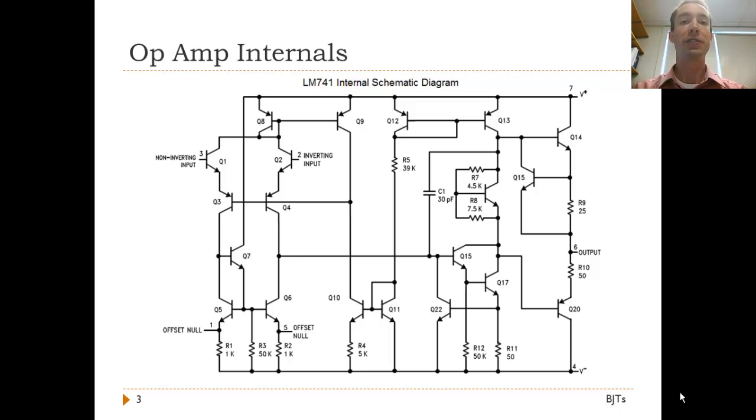An op-amp is composed of tens of transistors. The figure here shows the internal makeup of the very common LM741 op-amp. The different transistors form different types of amplifiers and other elements that work together to provide the high gain, high input impedance, and low output impedance that characterize standard op-amps. Analysis of this full circuit, however, is beyond the scope of this introduction and is not necessary, as good analysis and design of op-amp circuits can be achieved with a much simpler model of an op-amp.